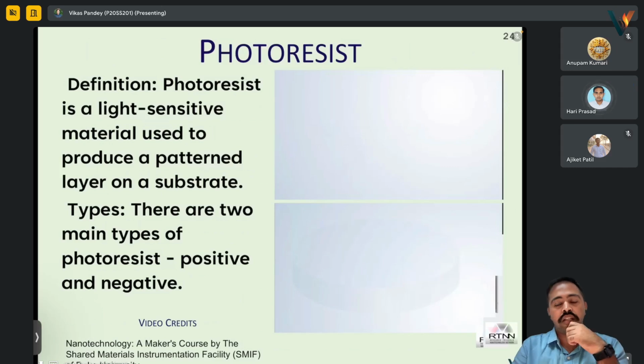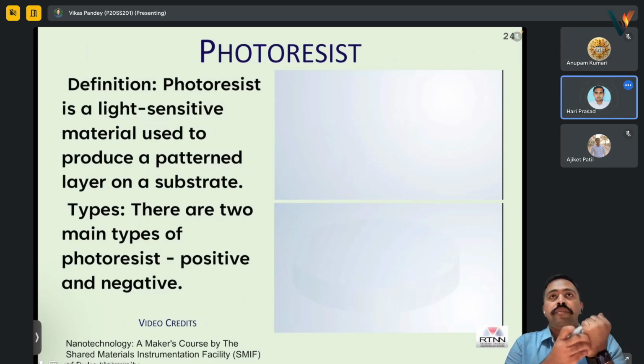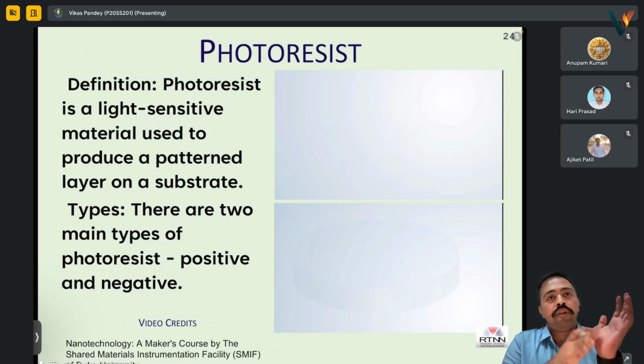Sir, is this designed using a laser? For a normal case, a mask will be laser written. At IIT Jodhpur also we have a laser writer facility. But if you are going for smaller dimensions, then we go for e-beam or deep UV lithography to make that. Got it?